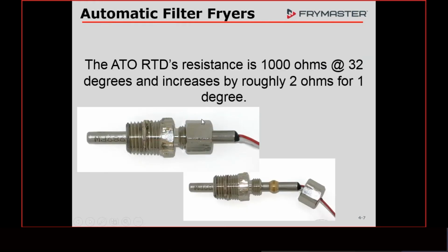Here are the temperature probes that we use on there. The resistance value of these probes is exactly the same as it is in a temperature probe. If you don't have a tech reference manual, you can go online and download it. That's the manual that we use to teach our level 2 classes, our field training and so on. In the back of the book, there is a resistance chart.